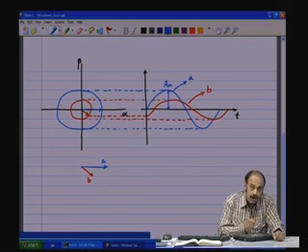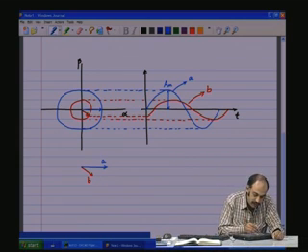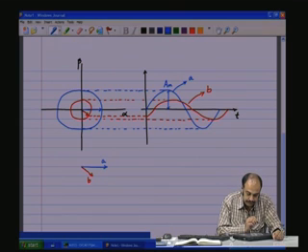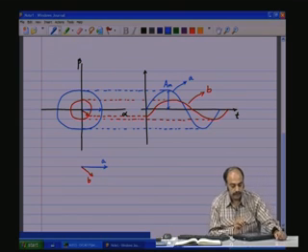Or in other words, if we have a space vector like blue and the space vector like this red as shown here with the space difference, and then if they rotate at some given frequency, both rotate at the same frequency, then on projecting onto the temporal coordinate system, they will evolve into the sine wave as shown here, where the red sine wave is lagging the blue sine wave. So, which means the red phasor here is lagging the blue phasor. This is the meaning of this particular thing.